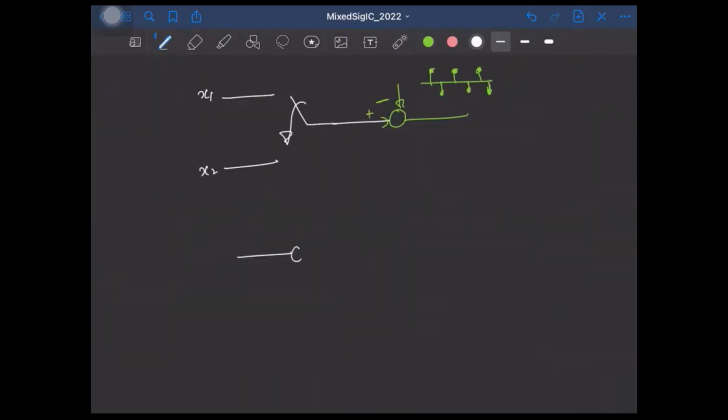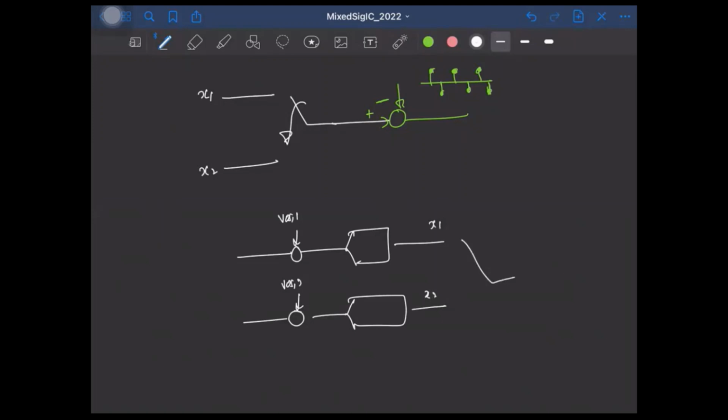So I have the two-way multiplexed, two-way time interleaved ADC like this, right? So these are the offsets. So this is X1 and this is X2. Okay. So what I can do is I can give a signal which could be a 0 also, right? I'll give a 0 signal, right?